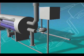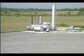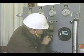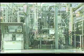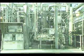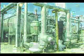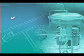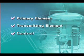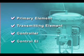to the desired point. In a simple operation, it may be possible for one operator to manually deal with all process variables and control them. But as the process becomes more complex or spread over a large area, it then becomes more than one operator can manually control. In such cases, automatic process controllers are installed. All automatic process controllers contain a primary element, a transmitting element, a controller, and a final control element.